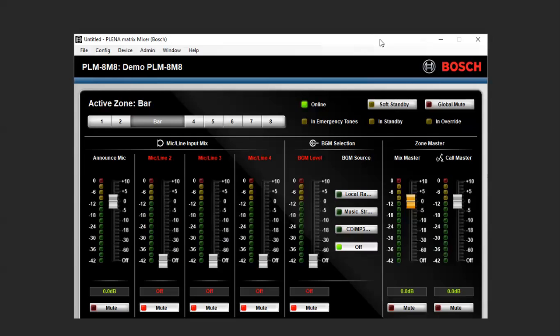Another one here, when we connect multiple call stations, we need to assign all call station IDs through dip switches. Can you clarify that step a little bit? Yeah, every call station is going to have a dip switch on the bottom of it, and those will need to be set before they're plugged into the system. That basically gives it the addressing and the monitoring from the controller.